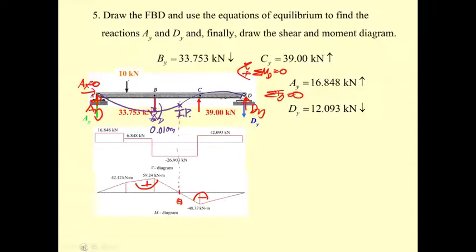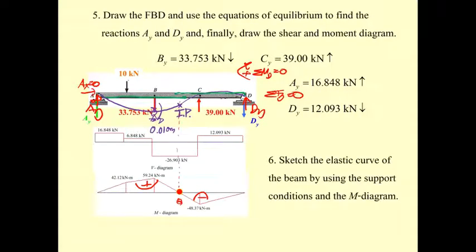Also, if you like, this portion mostly has the reinforcement like this. This one has the main reinforcement like this. That is going to be the elastic curve and also the reinforcement pattern, as you may put. But usually we don't prepare for the settlement, and the moment due to the settlement is going to be very large. Most of the time when we have settlement, we will see cracks in the structure.